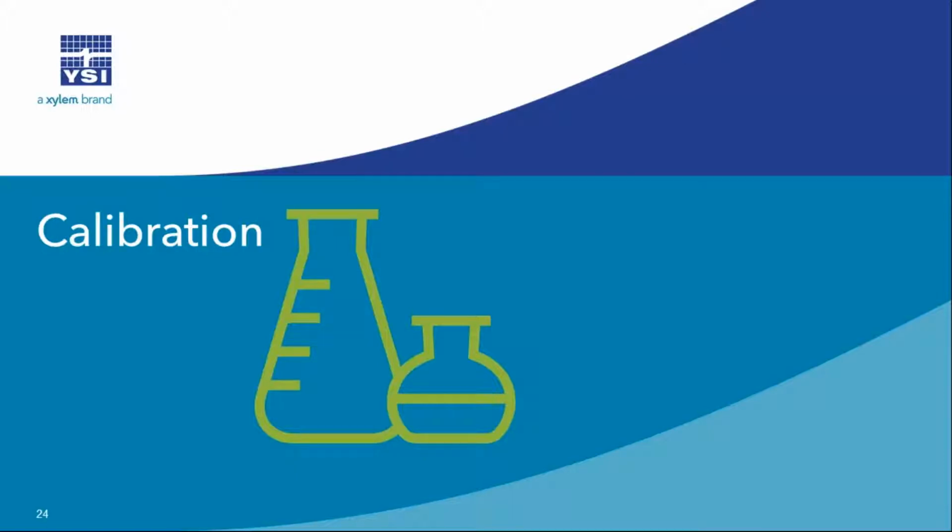So hopefully you're using the anti-fouling wiper, which will be really important, and you're monitoring turbidity and making sure that those sensor faces are staying clean. I would go out once a month and I would take some clean water with me and I would check the 0 point on that sensor. And if it looks tight, I would keep going. I would go up to 90 days probably before I would recalibrate until I have a stronger confidence in that sensor. And as I said, a lot of folks using these sensors end up going pretty much a whole algae season without having to recalibrate. I don't advise that you expect that out of the box. I advise that if you're new to the sensors and trying to develop your regime, you take a little more conservative approach like I just recommended.